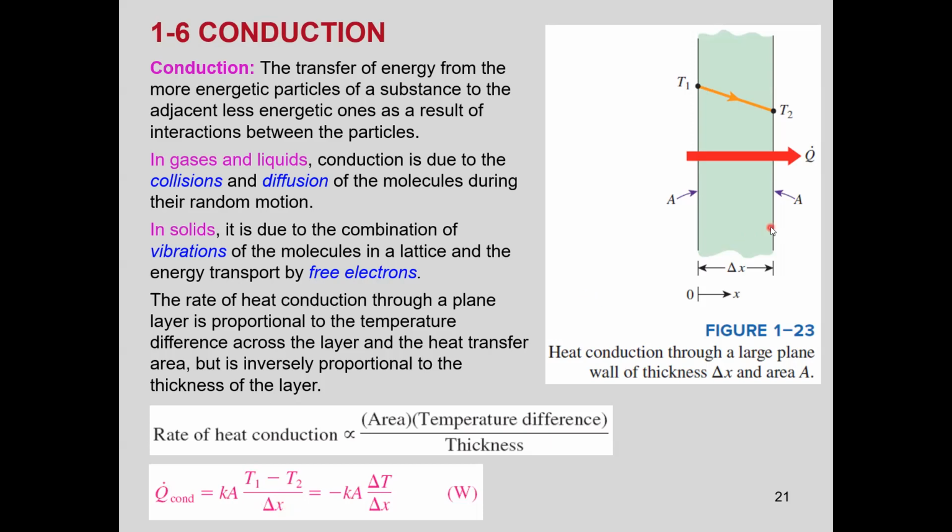But different walls have different heat transfer characteristics, right? So we need another property which accounts for the wall material. That property is K. What is the name of K? Anyone? K is the material property. Because if this is copper, brick, concrete, or wood, heat transfer is different. To account for this material difference, we have a material property in the equation, which is K.